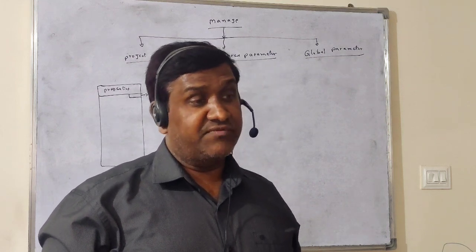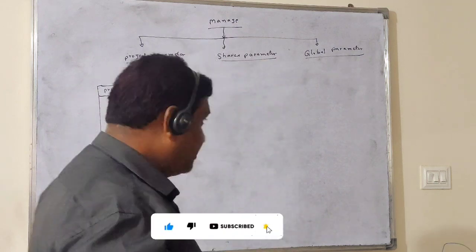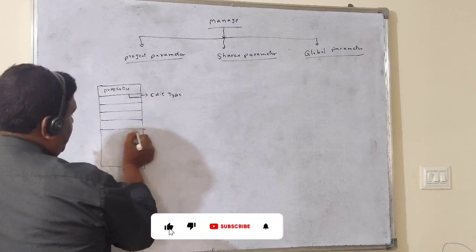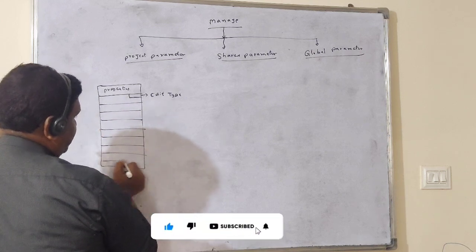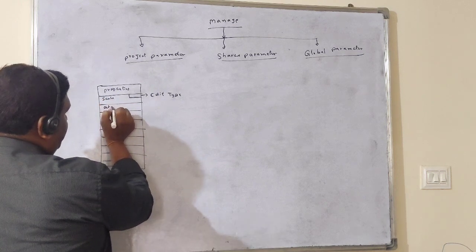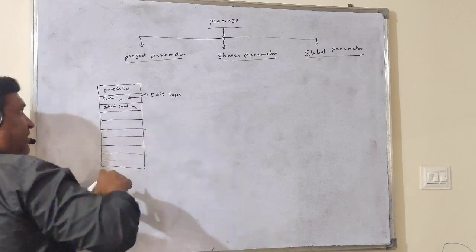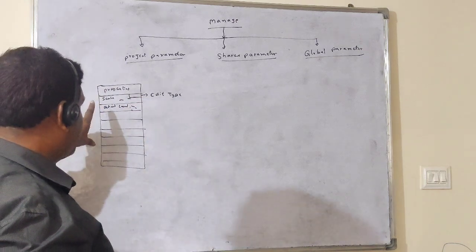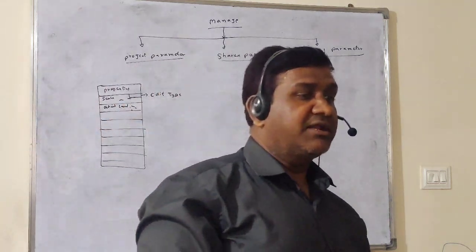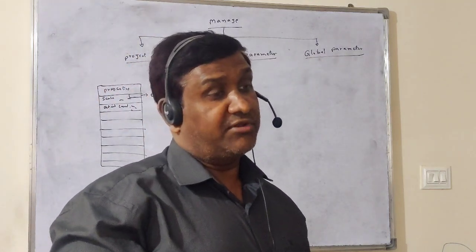This Edit Type menu is very important, because in the properties toolbar there are a number of options, like parameters. The first options are scale, detail level, and many more options here in the properties toolbar. Am I right? Apart from these options in the properties toolbar, there is one more menu. If you click that Edit Type, in the Edit Type dialog also you will find some more properties.